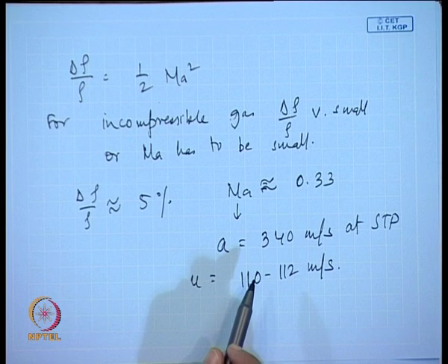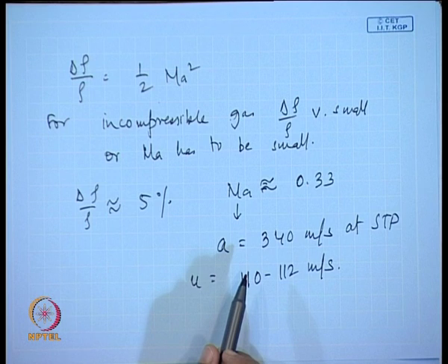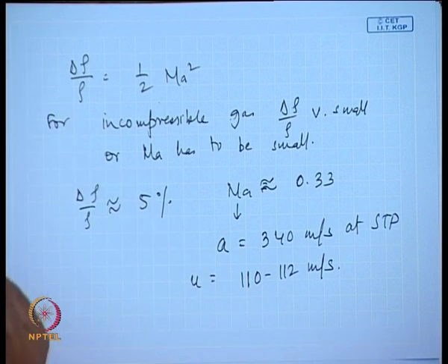Okay. So, from this we understand why under most circumstances we can treat the gas phase as incompressible, but if you do so, you can complete the calculations, but at the end you have to show that the density changes were negligible. For any problem that you do, you can assume incompressible flow. You can do the entire problem. We will be doing a problem tomorrow which will enable you to understand this. But at the end you have to show that compressibility effects are very small. Okay, that has to be shown at the end.